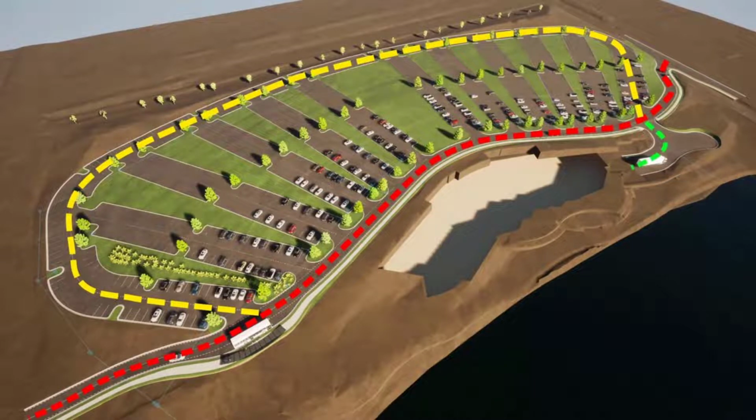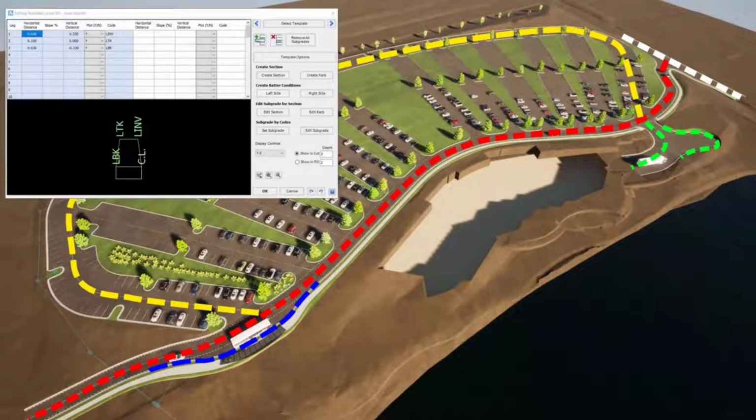The green line is the access road, and the second green line is the knuckle that we're going to use for the vehicle turning of the trucks in that area. The dashed white line on the right hand side is the existing road, so we want to widen that and have our main road merge into it. And the dashed blue line just on the left hand side is where we're going to do a widening for the bus bay.